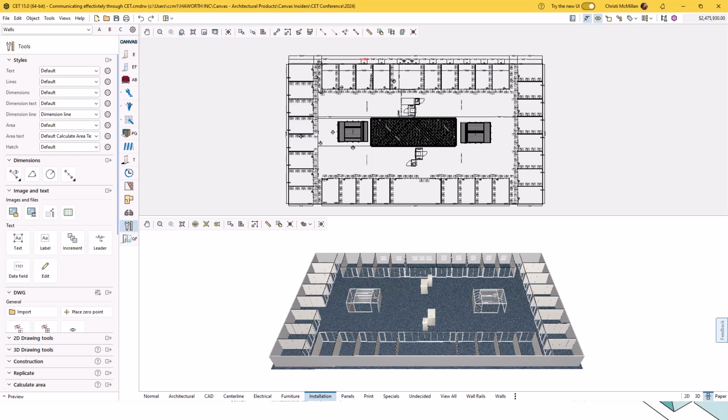There are also angle dimensioning tools and radius dimensioning tools, as well as the 3-click, 2-click, and additional options to your chain dimensioning in here as well. This is within your tools tab under the dimension section. You get additional dimension options. These two are the ones you're probably going to use the most.